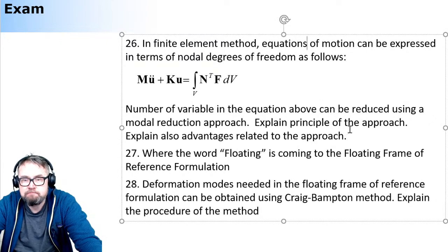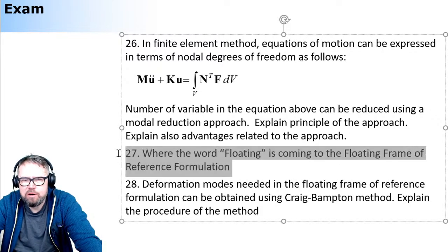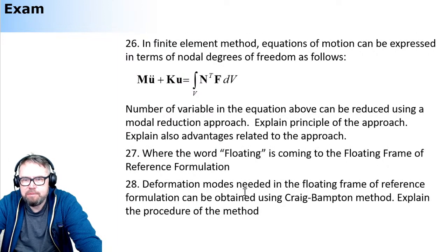Explain how it goes. Then the kind of question that I like, where the word floating is coming in: in the floating frame of reference formulation, what is the floating standing for? Deformation modes in the floating frame reference formulation can be obtained using the Craig-Bampton method. Explain the procedure of that method.